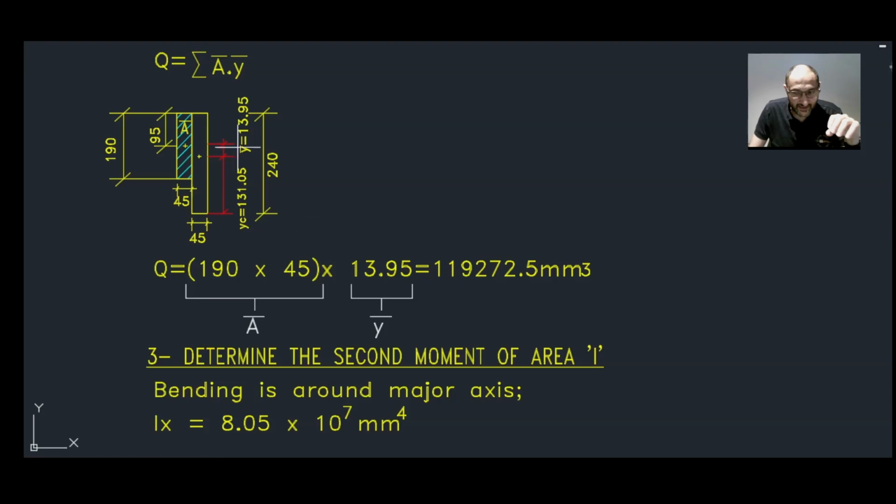Well, the simple answer to this question would depend on the value of the applied moment with respect to the cracked moment of the concrete. Now, the cracked moment of the concrete would generally include the tensile stress capacity of the concrete minus any shrinkage stress. So we would need to look at the bending moment in the whole beam, and check which areas of the beam are cracked and uncracked and use the relevant values.